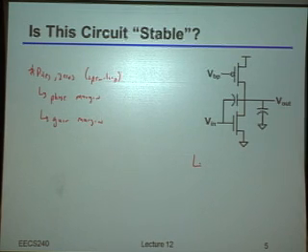There's a 3-letter acronym that I'm about to... There we go. You're assuming it's linear and time invariant, right? Because when you say there's a pole and a zero, by definition, you have to assume that it's a linear time invariant system. Okay? So now let me ask you guys, is this circuit a linear time invariant system? No. So first of all, it's certainly not linear, because for better or for worse, the transistors are not linear, and if they were linear, then no one would use them. Okay? So transistors are not linear, and I would actually even claim the circuit is not necessarily time invariant either.